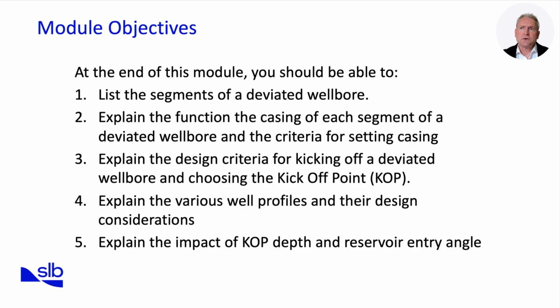The objectives of this module extend the foundation from Submodule 1. You should finish with the ability to critically evaluate how kickoff depth, trajectory geometry, and reservoir entry affect overall well performance. As a drilling engineer, trajectory planning goes far beyond simple geometry. Every choice impacts torque, drag, hole cleaning, and long-term wellbore stability. We'll discuss how to balance mechanical and hydraulic limitations against reservoir requirements. This involves careful casing design, realistic dogleg severity targets, and alignment with the completion strategy.